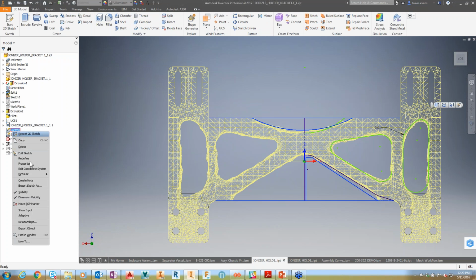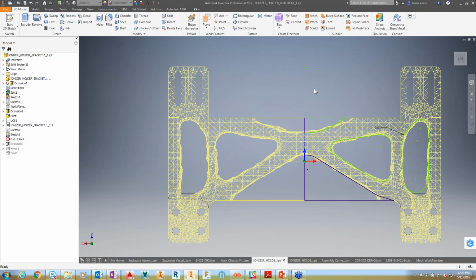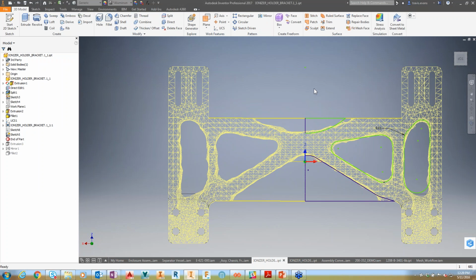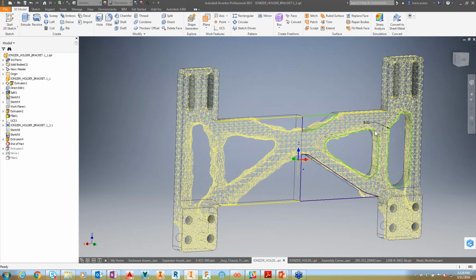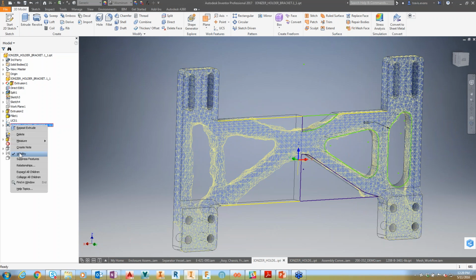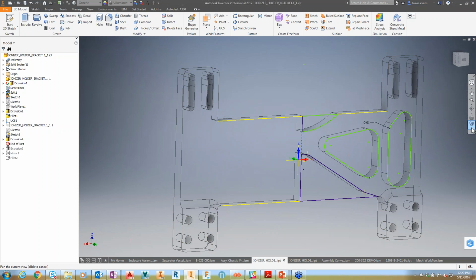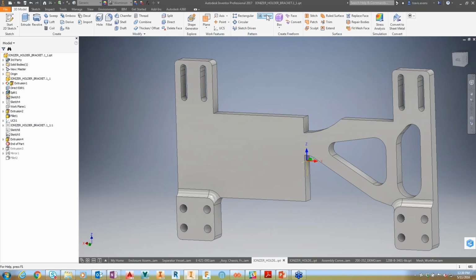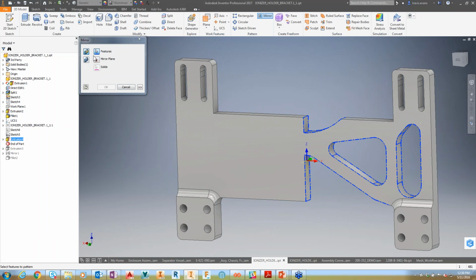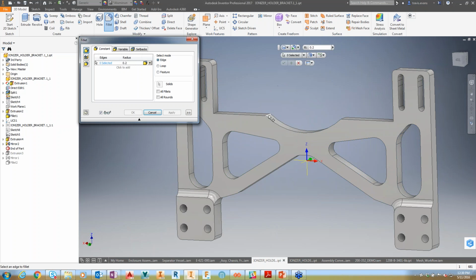So here you can see a sketch that we built right from that geometry. Now I can use that to create my traditional subtractive manufacturing features. And now we can say, let's cut that out. Let's turn off this visibility here and turn this back to shaded geometry. So we can build this out using regular modeling techniques. We'll use a feature here, mirror that about that face, and now maybe we'll add a fillet to this top face.